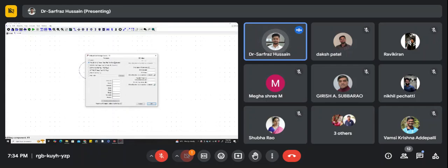So you can see the definition of how you can call a pulse: V1, V2, delay, rise time, fall time, on time, period, and the number of cycles. So this is how you can call a pulse. Let's say the initial value is 0, then 1.8, delay is 1 nano, rise time is 1 nano, and on time let us keep as 50, and time period as 100 nano, and number of cycles as 2.